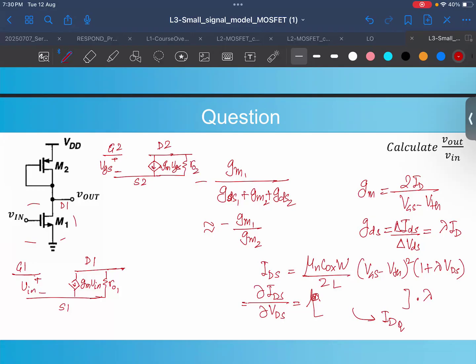And now you have to merge, because D1 and D2 and G2, they are merged. So G1 and G2, this will merge, right? This is because of this shorting. And when we see this is shorted, and if you now do the D1, so now I'm just bringing it here. Then you see what would be on the other side. So this is in parallel, S1 and S2, because S2 is also shorted to AC ground, right? This is anyway shorted. So S2 is also shorted to this.